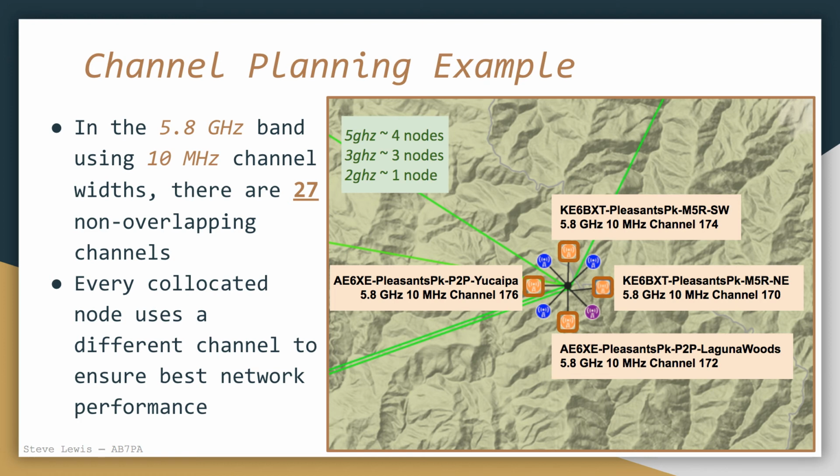Your selection of channel numbers may depend on what else is already happening at your site. For example, you may find that using a lower or higher frequency range yields better performance based on the existing RF signals that other equipment at your site might already be generating. A spectrum analyzer could help you during your site survey since it can identify frequency ranges which are less utilized, and then you can assign channels within that space to your AREDN nodes.